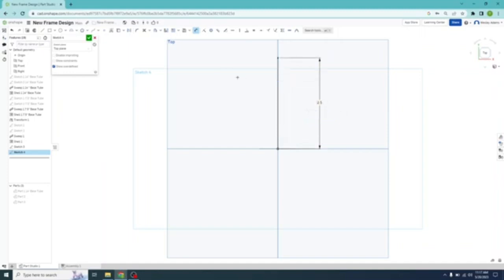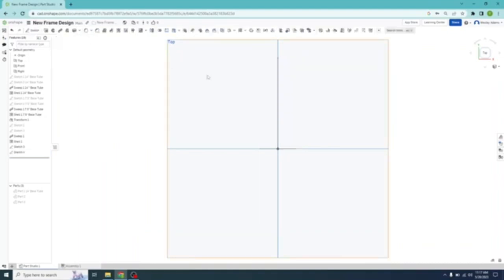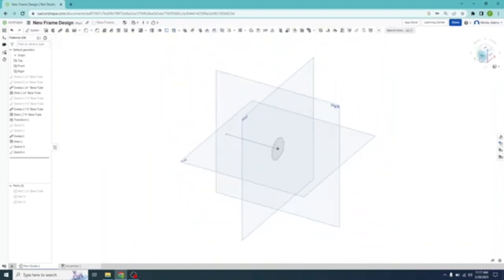Dimensions are set. We'll close this sketch out and we'll sweep that path. So I'm going to go to a different view. So that's isometric view. We're going to left click on the sweep, make sure that solid and new are selected. We're going to come down here and select the outer part of that circle by hovering over it, and then left clicking. Now it says face of sketch 2, so we know it's selected it. It's asking us for the path. We're going to left click on sweep path, and we're going to click that again. Now it swept the path.